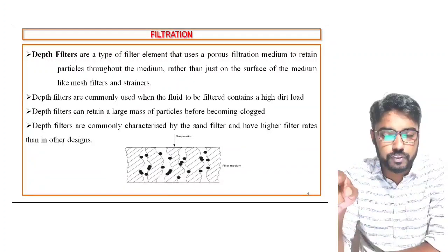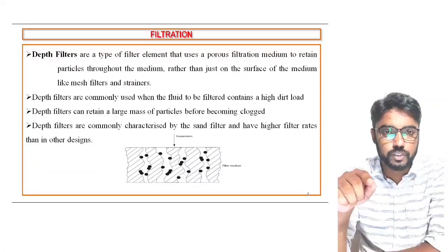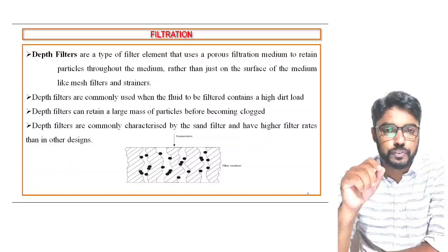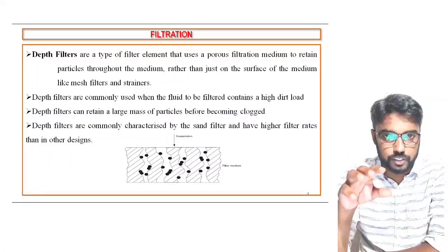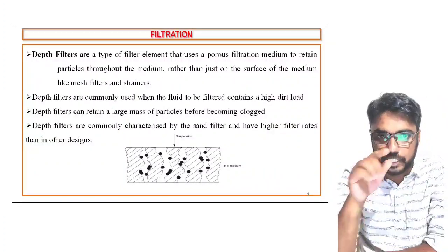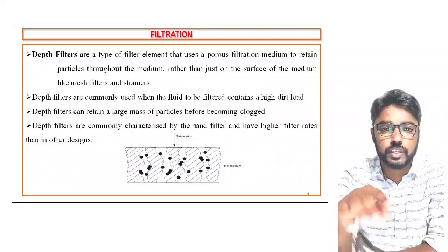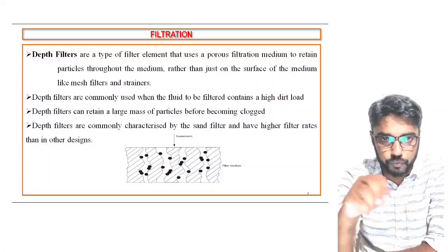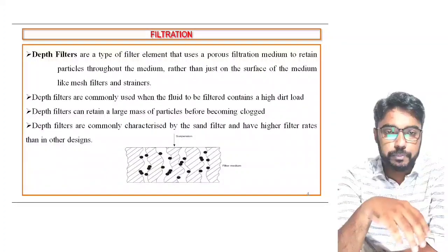But in the case of surface filters, that means screens or mesh filters, the solid particles will be accumulated on the upstream portion of the filter. In the case of depth filters, the solid particles accumulate all over the filter medium.